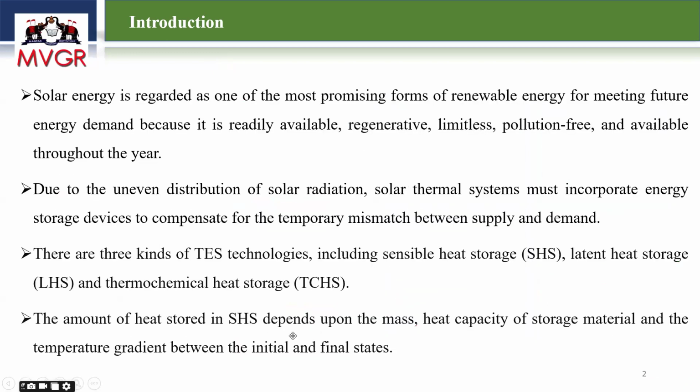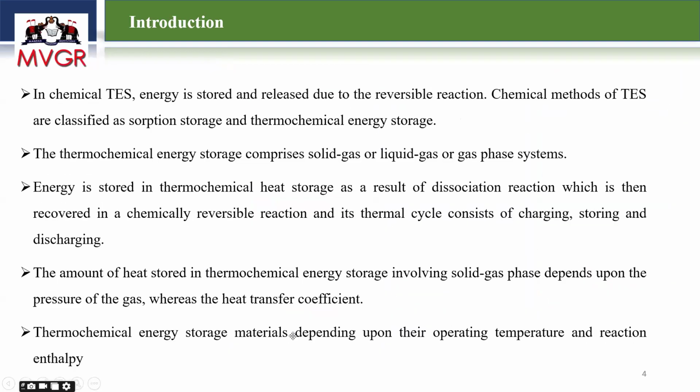Let us take another system, that is the thermochemical energy storage system. Mainly two kinds of systems are available: solid to gas and liquid to gas, or gaseous phase systems. The concept is very simple. Suppose two materials are there, and at a certain temperature these two materials undergo some reaction. Let us take one material like calcium chloride and water.